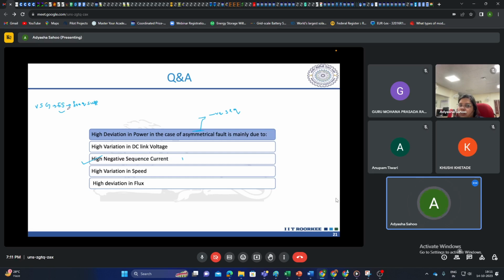So that will act as a virtual synchronous generator. And if you remember the examples of utility scale deployment we had in week 3, I don't remember the exact examples, but there were some cases where these energy storage devices have been deployed at utility scale for frequency support. So you can envision that this is basically a special name that has been given. But in actual, it is a storage which is giving the ancillary support of frequency support.